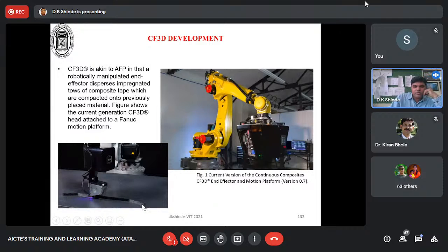So you want to print. This is one kind of channel that has been printed, so this is the outside of this chamber, and inside all this there. Here is the extruder. The entire tape is passed through the nozzle, like what we have discussed so far. The nozzle was a wire, but now in this nozzle you can pass pre-preg tape of a certain width, the width of the component you want to print, and you deposit according to the G code and STL file.